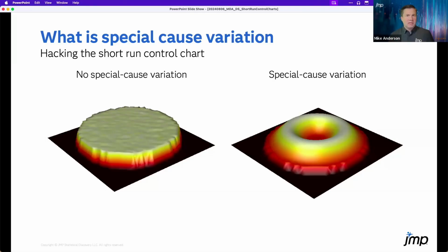But when we come to our deposition tools or our etch tools, we can see this topology, which is a bit of a problem. Quite a lot. And this is a little bit exaggerated, obviously, but it's this toroidal shape we see pop up all over the place. And you may not first be able to notice it because the sampling plan sometimes masks it. It'll show up as a dot here and maybe a blob over here, but they all are on the same radius. So it's always a good habit of transforming the data to go, oh, are those connected somehow? Just as a matter of course, but in this case, that's the problem.